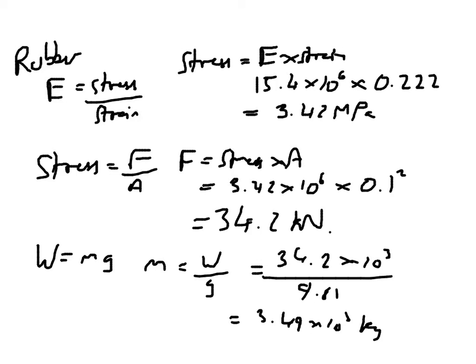There are a couple of other extra little bits just at the end of the Poisson ratio section. If the equipment is vibrating, then the forces on the pad will be variable through the vibration cycle. So you're going to be thinking about the average load being equal to the static load. The frequency and the amplitude of vibration affect the maximum force on the pad, and can be much higher than the static loading that we've just talked about. And there is an equation that relates them on slide 26 of the PowerPoint.